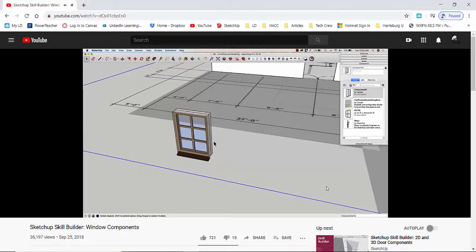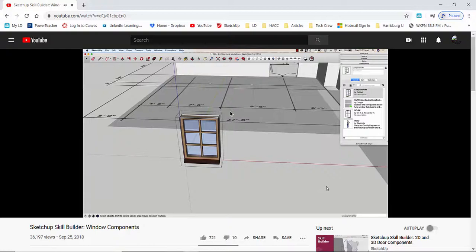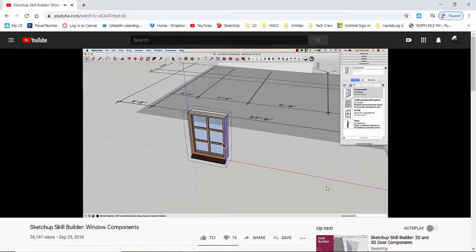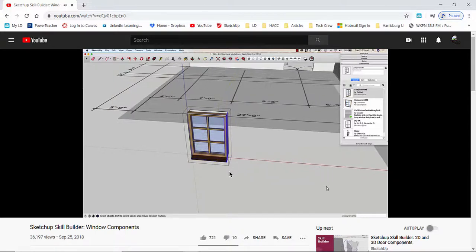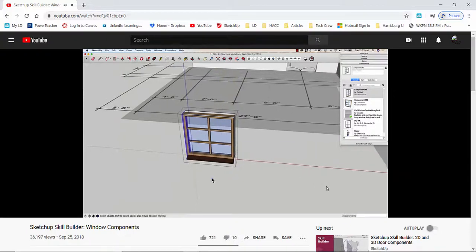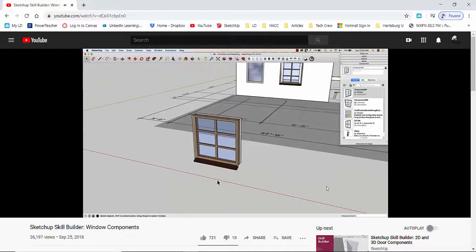I can bypass that issue by coming in here and doing things like selecting only the geometry on the side. Hold on, let me explode this geometry out. This is the process I would have to go through to make this work. And then I could take these pieces, the vertical pieces on the right, and scoot them over. Say I want it to be a foot bigger, so I could go 6 inches this way, and then grab this side 6 inches this way, and there we go. And that would work. That is totally an option.